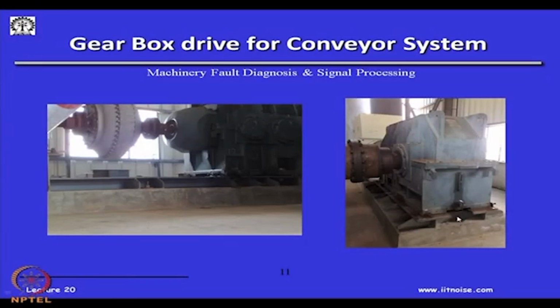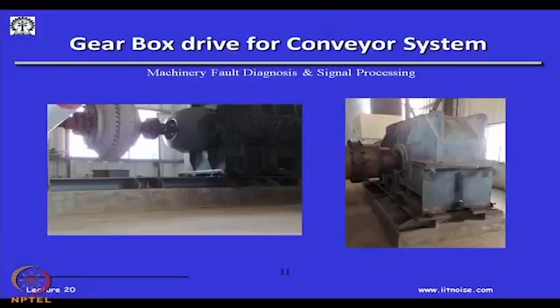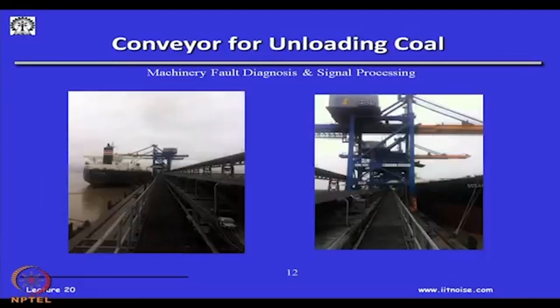On top of it, if you do not do a perfect alignment, a lot of sources of high vibrations can arise. No matter that you may have a very good new gearbox, new motor, new bearings, the misalignment in the foundation is going to give you high levels of vibrations. And in fact, this is where the ships come in